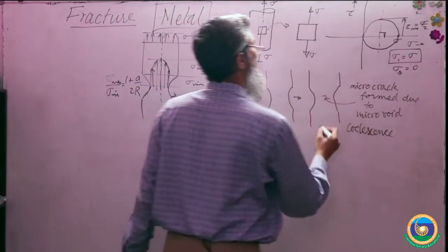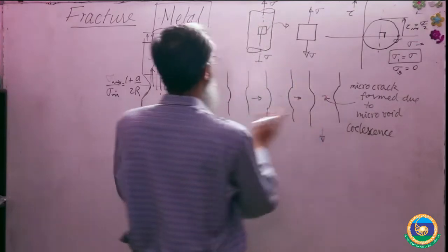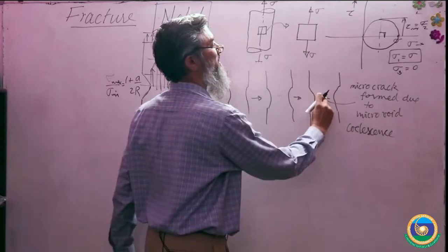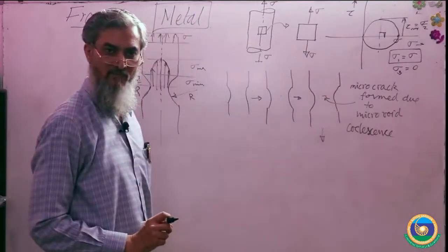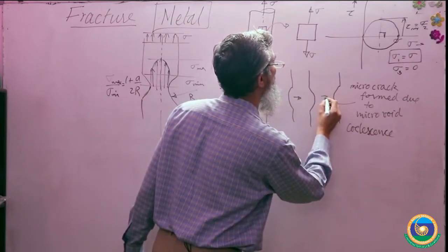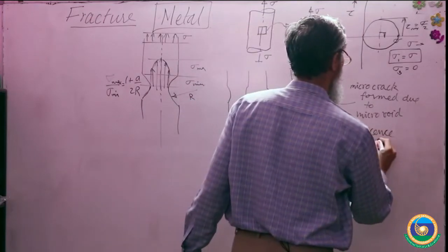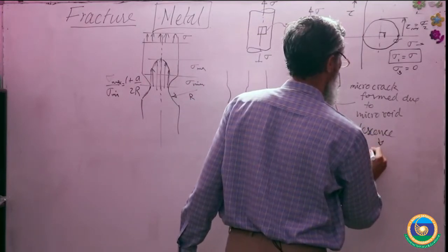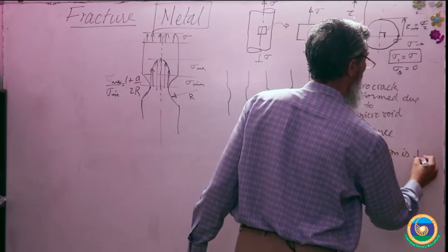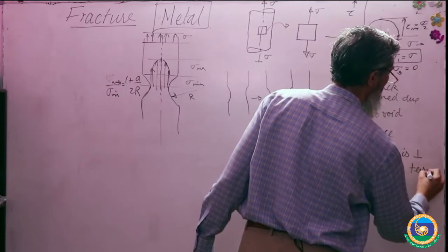Once this has been formed, if you stop the tension test and cut and polish, you will find a crack in the center. If you go on loading, this crack is going to increase. The direction of the crack is perpendicular to the tensile axis.